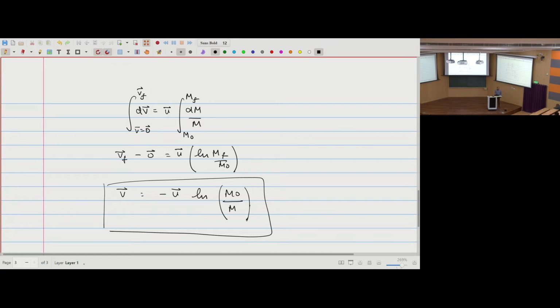If for some reason I am designing this for space, and if I burn the gases very quickly, the temperature increases, because I cannot get rid of that amount of heat that quickly. So, my temperature will increase in the engine, and that could lead to a meltdown, because the materials I am dealing with do not allow high temperatures. So, this is fine for me, because I can burn the gases slowly and still achieve the same velocity, no problem.